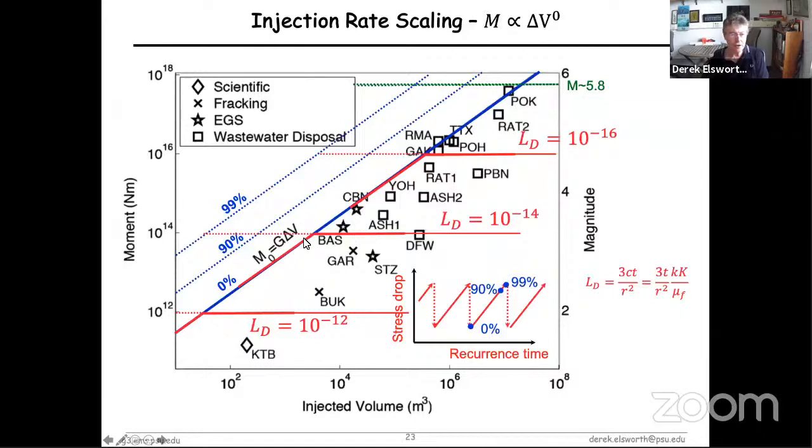You've reached the peak pressure in the reservoir at this point, and now it's leaking out of the sides just as quickly as you're adding it. So the magnitude is always going to be the same. If it happens to be a lower permeability exterior material that it's leaking into, then the pressure will keep on rising until you get to this point here, and then it will reach a steady state. The event you get will be larger, because the pressure within the reservoir will be larger itself. So I think that's the physical explanation of what's going on in this particular system.